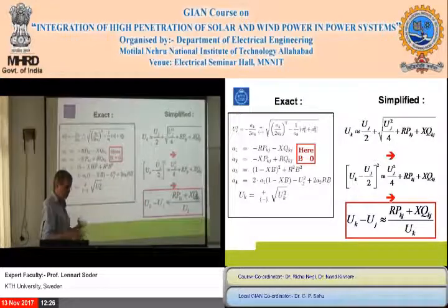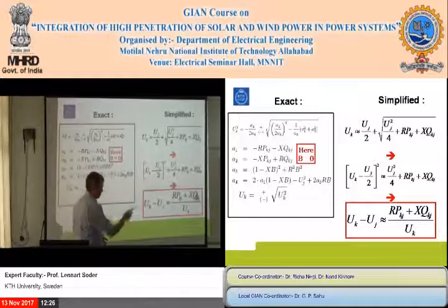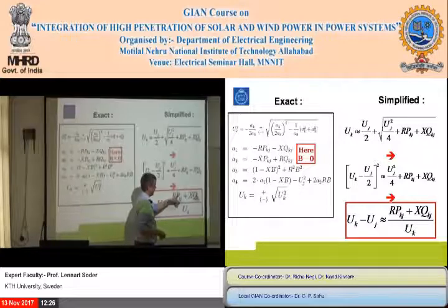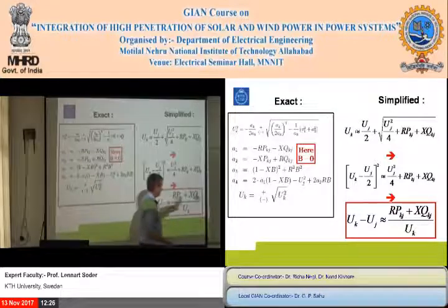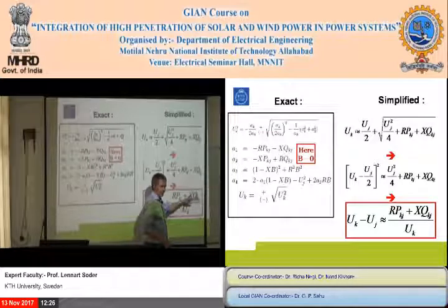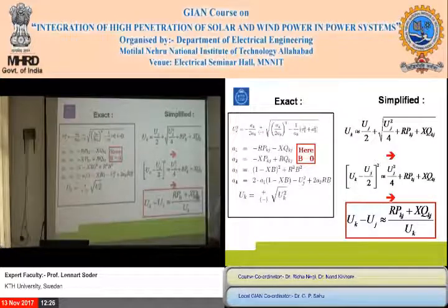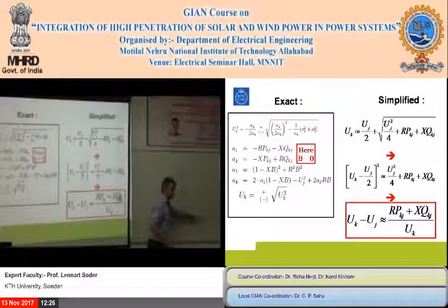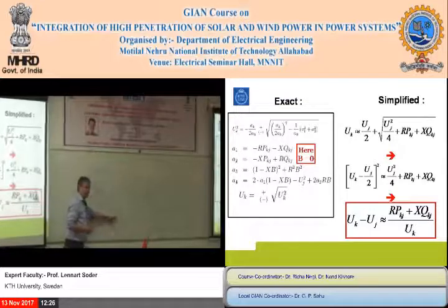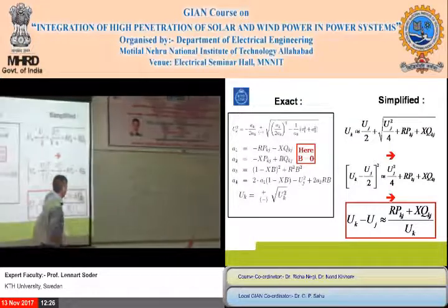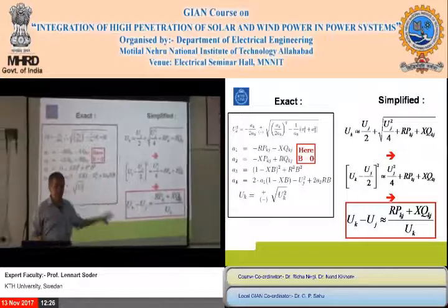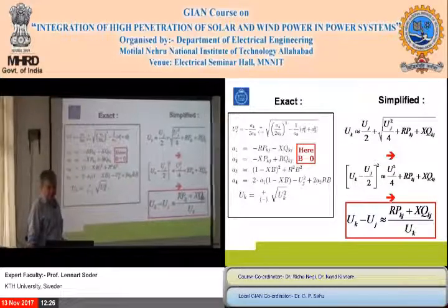So then you have these two issues. One is to keep the local voltage using the wind power plant. You get more and more wind power, and then you can compensate that with reactive power. That's very nice, but then you need an X. On the other hand, if you want to supply reactive power, and you have voltage problems because of the P, then if you have a very low X, it's no problem to supply a lot of Q. So here you have just this small equation, you can get a feeling about how it works.